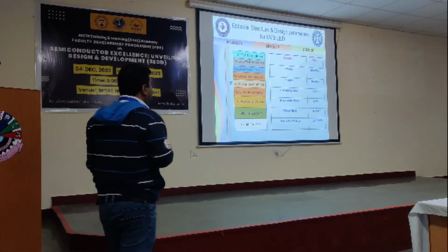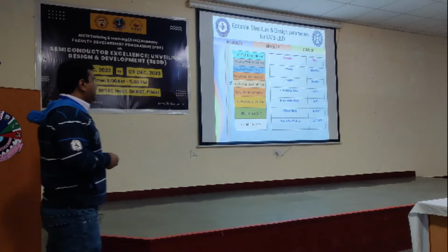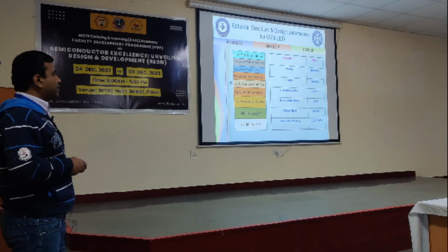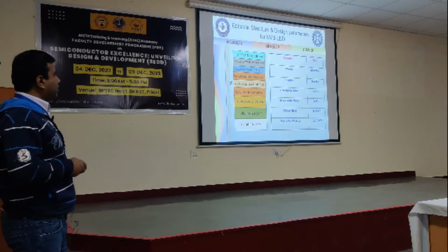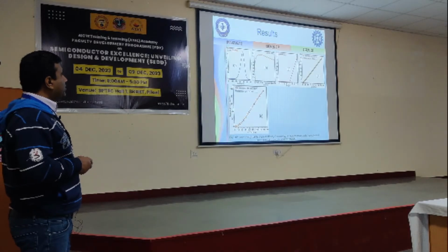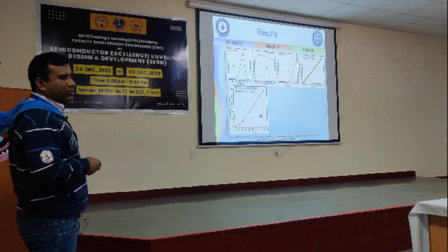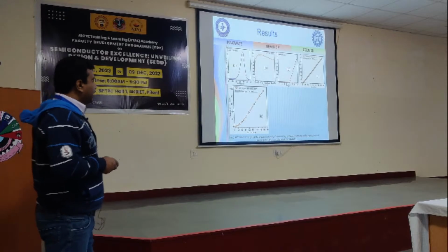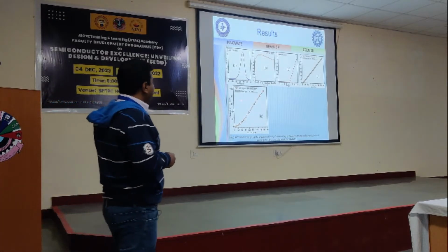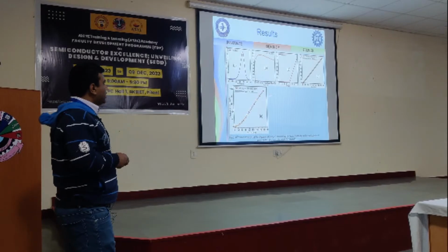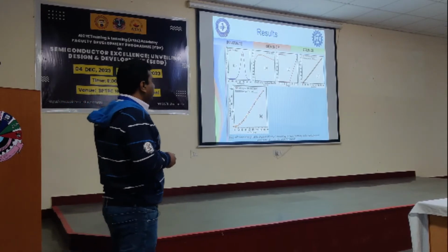Now this is another device where UVB should be achieved. This is the corresponding structure, and all the simulation parameters have been represented in tabular format. You see the UVB 295 actually falling into the UVB region, and all the related internal quantum efficiency and output power for the circular pattern electrode as well as the finger electrode we have determined.